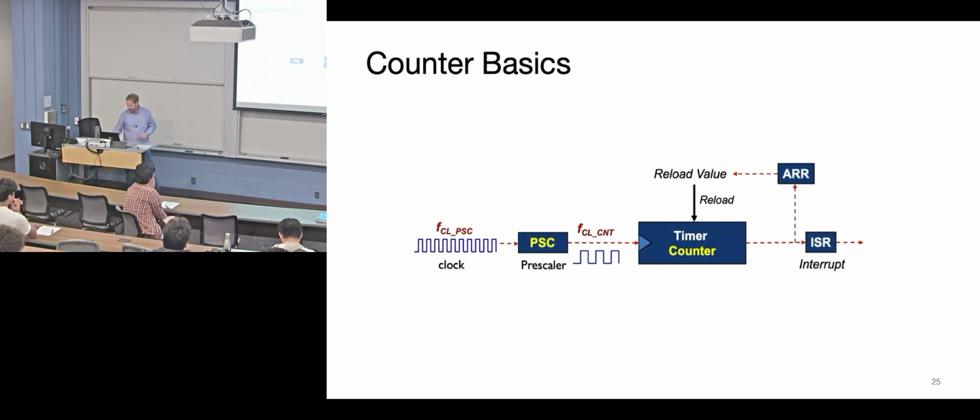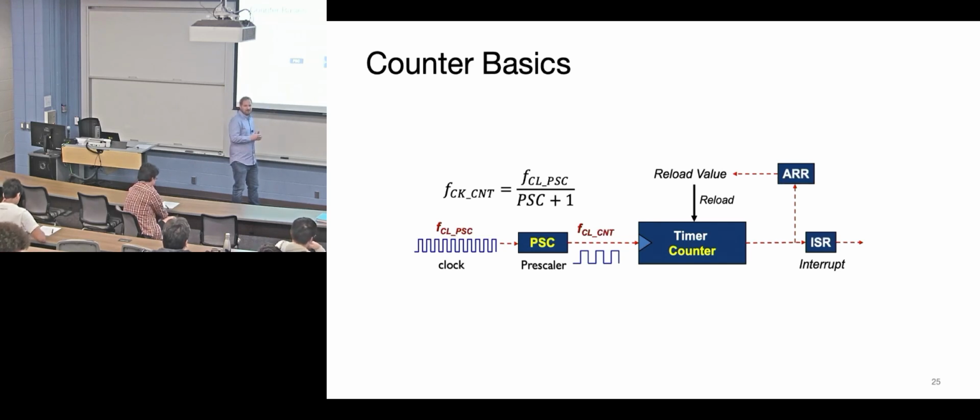Is this the one with it on here? Yeah. So here's your prescaler. There's your prescaled value. Your clock goes in, you get this value out. Basically inside here is just a little counter that's going off and then setting a rising edge when you've hit that value. And so that's why you can divide by some value, if that makes sense.